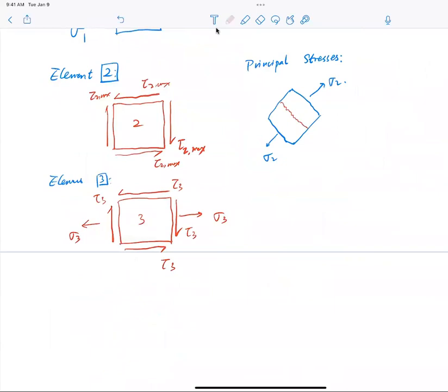Now, if I look at the principal stress state, it looks just like the compressive side, right? You don't need to rotate too much. Basically, you have almost a pure tensile stress. So what does this tell you? It tells me that I can convert all the stresses in the beam into a principal stress, and I can start investigating the failure of the beam.